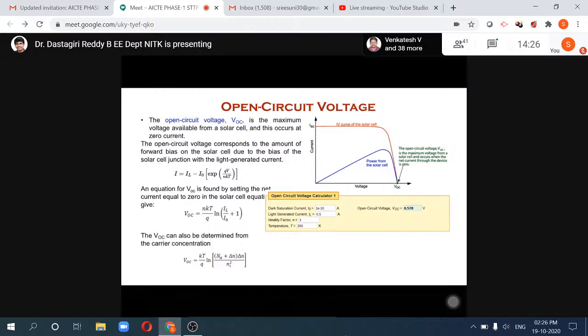So obviously we have compromised on that, and that is why there is a restriction on the cell voltage. The cell voltage, if you look at it, will always be around 0.5, 0.3, 0.6. It varies only in this range. That's the reason we cannot go to bigger voltages for an individual cell. These cells are connected in series and parallel, and that's how you get the total current or power rating of the PV panel.